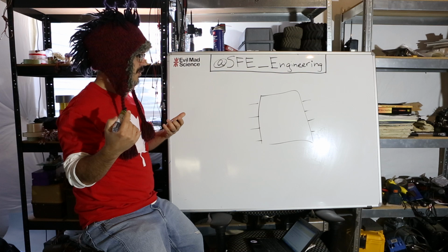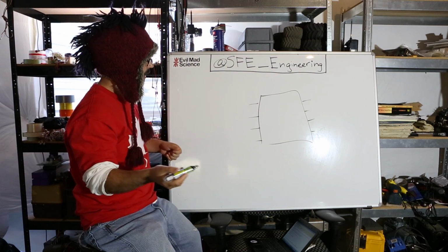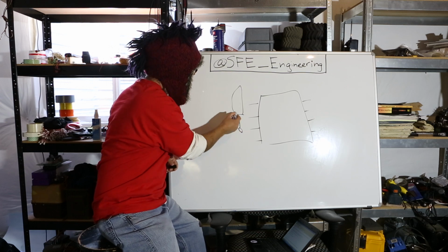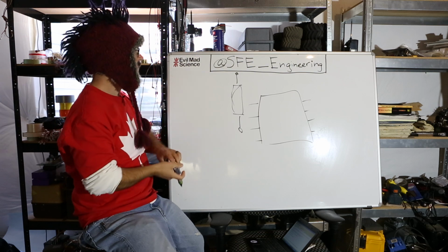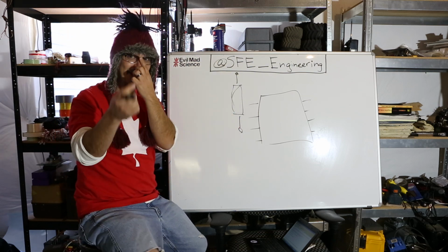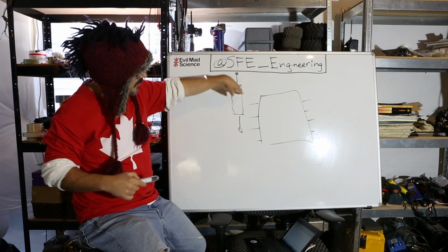Now, if you have to start using through-hole resistors on this, it's going to be kind of like that, and it's going to be goofy. Oh my gosh! So your loops are going to be bigger, right? And these are your traces back to high impedance pins. That's something I was a little bit stringent on in the last show. Your traces are going to be longer.